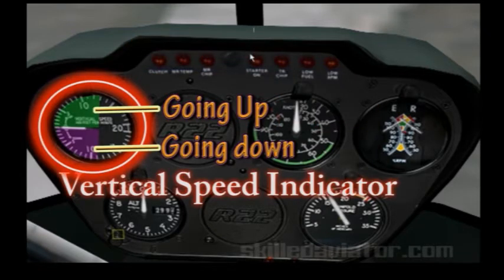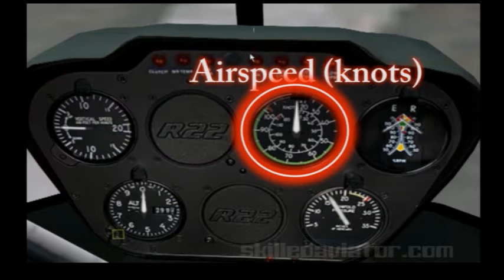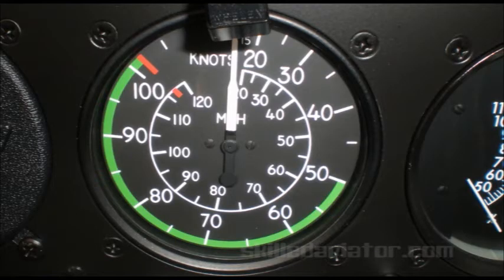Below this, on the left-hand side, we have the vertical speed indicator. This instrument tells you how fast you are climbing or descending, and if you are neither climbing or descending, then the needle will point to the left. To the right of the vertical speed indicator, we have the airspeed indicator. This measures the speed of the helicopter through the air. You'll notice there are some markings on it. Generally, try to stay in the green and certainly don't go past the red radial marker.